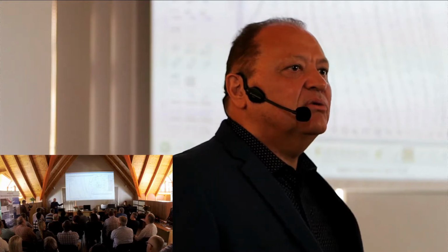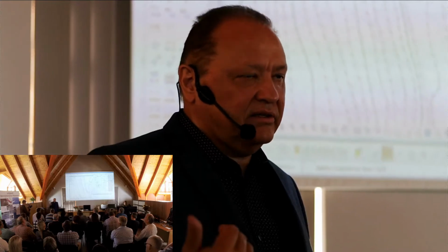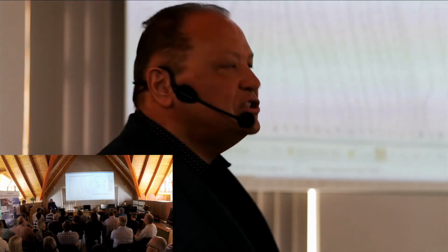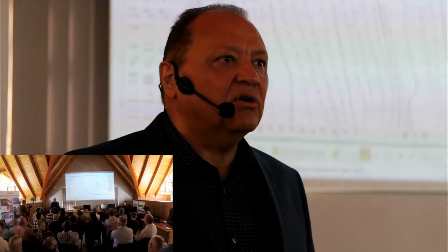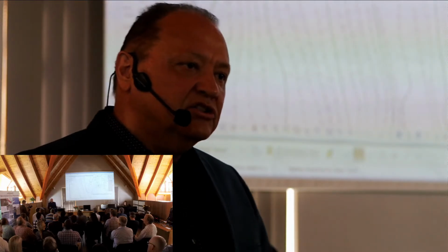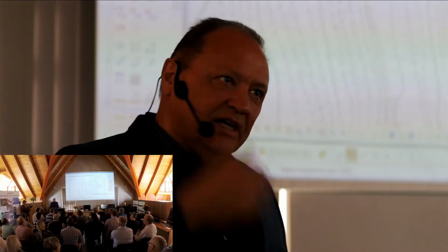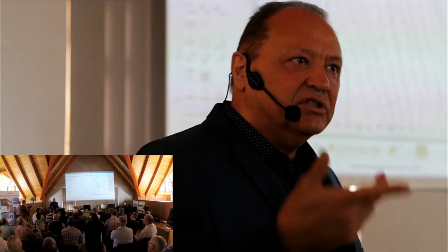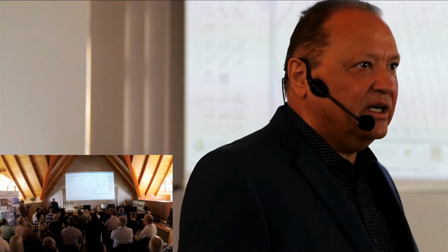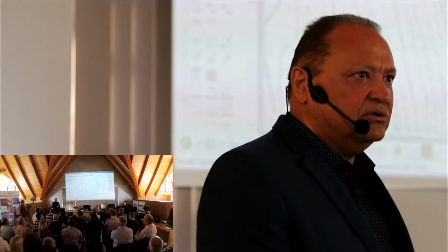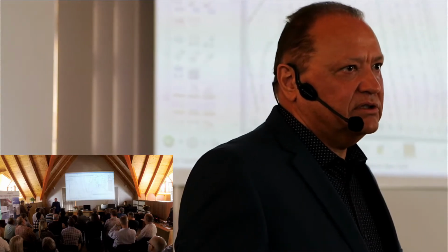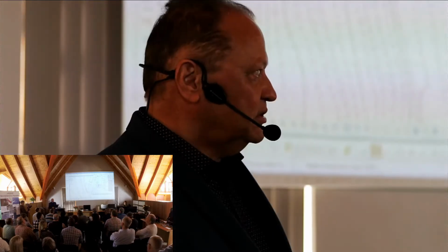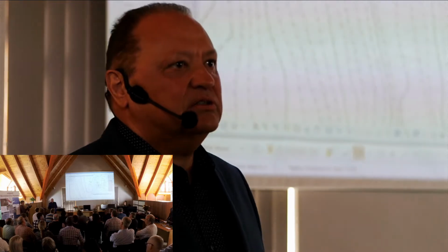What we would suggest with the new one is you give it new metadata information, and you say by date, this was before that date, and you switch off your auto delete button, which deletes the contours when you run them, okay, and then you just generate it in that area, and you will have the old contours and you will have the new contours, and you can filter them in or out by using your metadata. Now it would be much more efficient to use your metadata rather than swapping levels, etc. So there are numerous solutions, but I think the metadata you might find would be a better solution now that the metadata has been added.